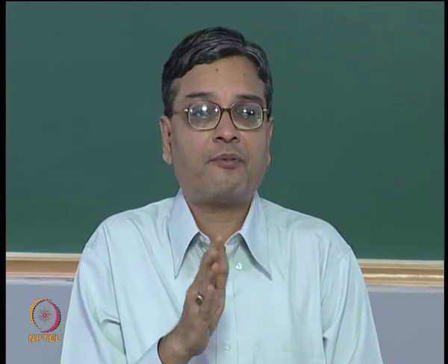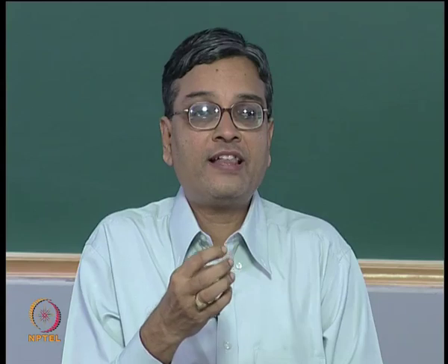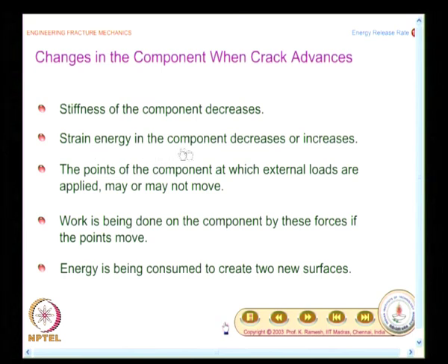On the one hand, it helps you to simplify the development of mathematics. On the other hand, it also provides a via media to calculate the energy release rate experimentally. So, it serves both the purposes. So, when you say strain energy in the component decreases or increases, that is actually dictated by are we having a fixed grip situation or a constant load situation. So, if I have a fixed grip, work done by the external forces is 0.